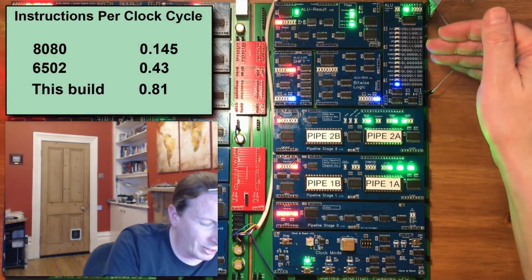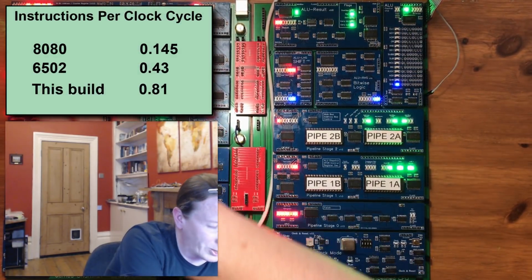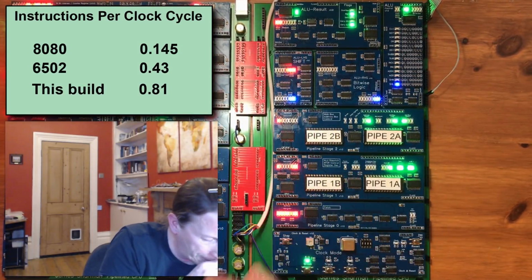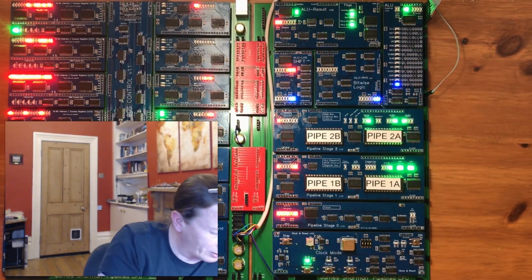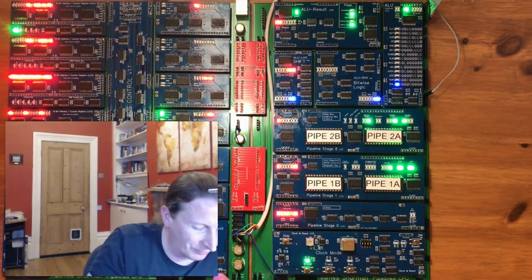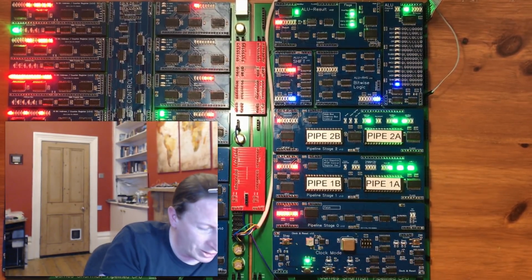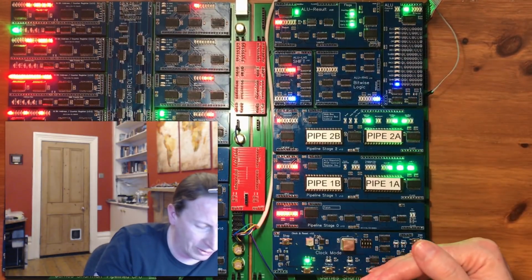All of my ALU operations, my 16-bit moves, increments, decrements, they are all single cycle operations, as are all my register moves. The things that take longer than that are anything that accesses memory. And the simple reason for that is I can't fetch an instruction while the memory data bus is being used for something other than the fetch unit. So it's only memory accessing instructions which are able to stall the fetch unit and prevent me from getting every single cycle dispatching a new instruction.